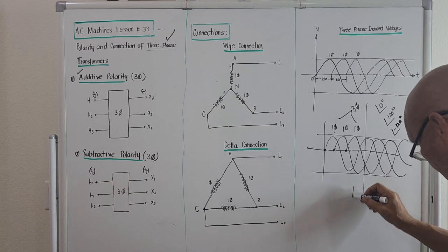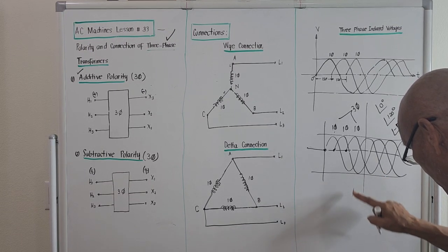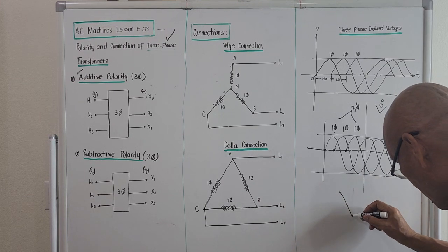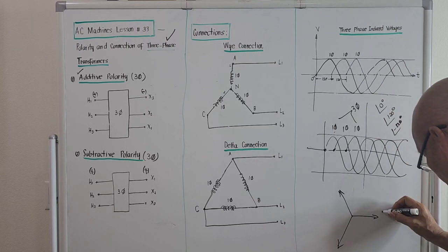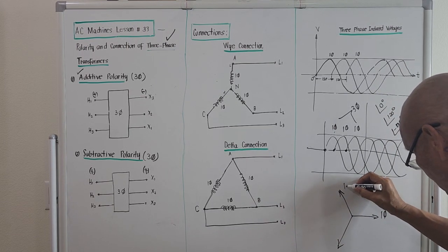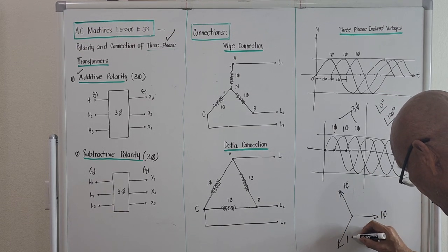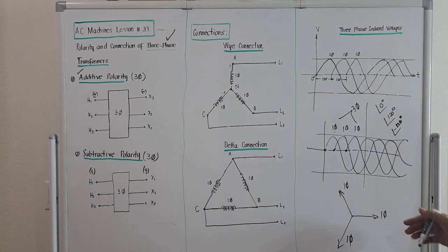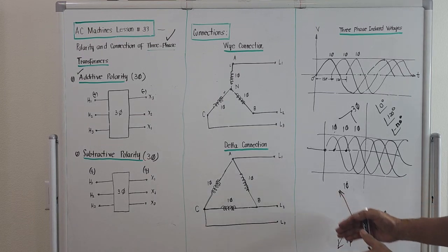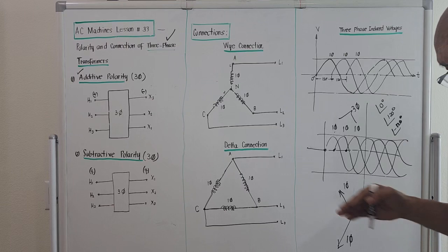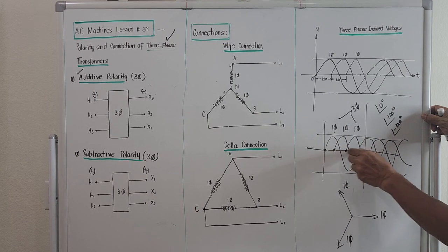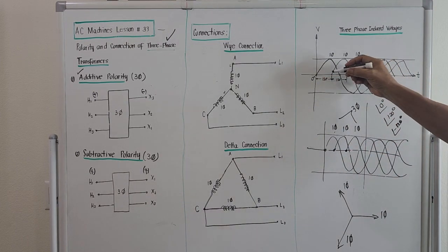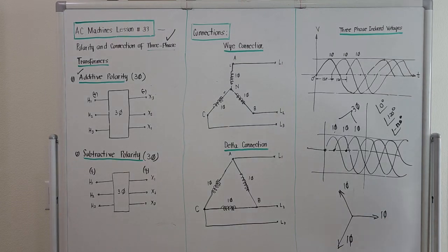So if we try to bring out the so-called waveform, it will be something like this. This is for the first phase, this is for the second phase, this is for the third phase. Okay? The coming out of the voltages as they were induced on the windings will not occur at the same time. There is a lag behind of around 120 degrees. Okay? So it's like this. It's just like the graph of a satellite orbiting our Earth. Okay?